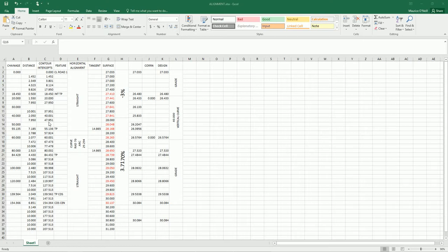When we come down here, we've got 55.135. We've got a bit of a millimetre difference there, and this is where we have to be very careful with those measurements and zoom right in to make sure that we're getting the correct intersection and what have you. And moving on down, so I've measured them all. We can see here from the tangent points that these are all little arc distances around the arc. And keying into the 60, we've got 1 millimetre, 2 millimetres there, a couple of millimetres there, 3 there, 2 millimetres there, 2 millimetres there, and so on.